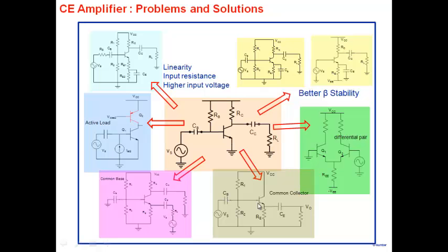But remember what we said? We took a case where you can make a common emitter amplifier with a gain of 1. You can get high input resistance and low output resistance. But the capability of the common collector is far superior to this, a factor of 10 or 20 times better in terms of giving you high input resistance and low output resistance. So it's several times better. If it were only a little bit better, we wouldn't have had a special stage for it.